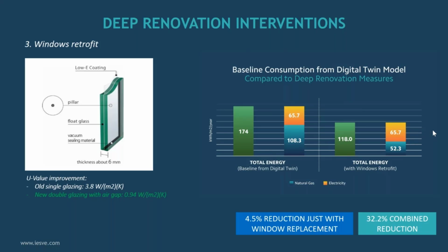And the same about windows retrofit. Basically, we had single glazed windows. We could use this solution, replacing the single pane with a double pane with vacuum in the middle of the two window panes. With this solution, we won't need to replace the window frame at all. So the traditional aspect of the building, which most of the times won't allow you to replace the frame of the window, will still be untouched with this intervention. We are really still replacing the window pane.